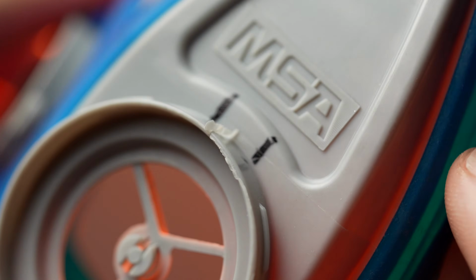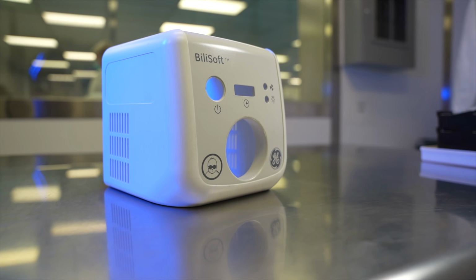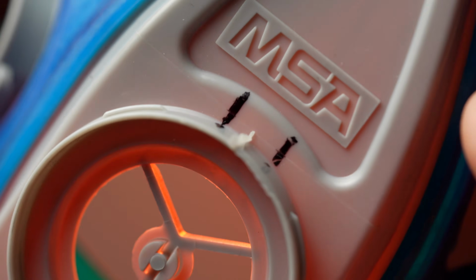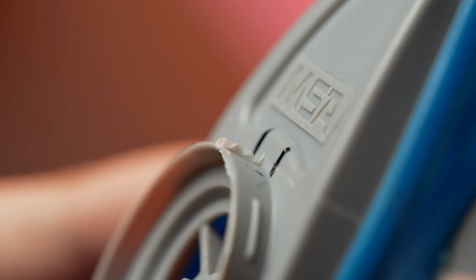Today, let's look at some of the most common injection molding defects and the solutions that we use here at Crescent Industries to consistently produce a high-quality part. Perhaps the most common injection molding defect is flash, which is simply when a thin layer of plastic flows outside of the mold cavity, usually along the parting line where the two mold halves are pressed together.